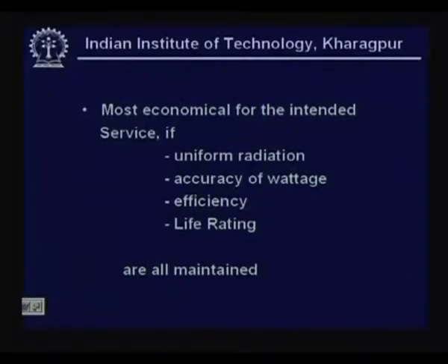And in order to have economic service for the intended application, we try to design the filaments for uniform radiation with reasonably good accuracy of wattage, light efficiency and life rating. All are to be maintained, and that is why we saw how the survival rate comes. And in fact, I told you, if you design 100 units, it is possible to have about 80 of them give you the required life.